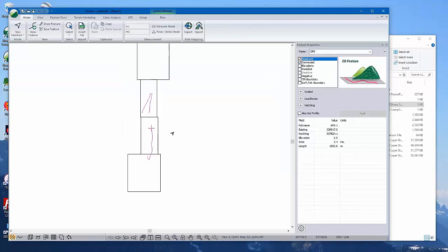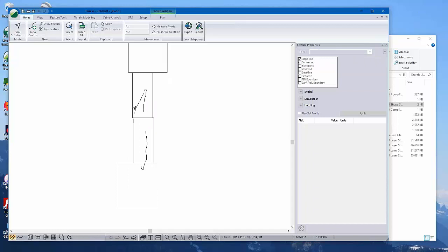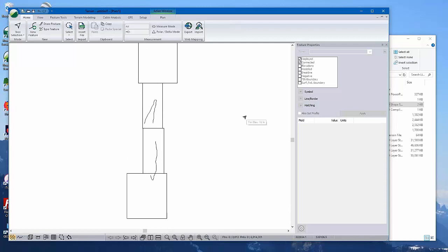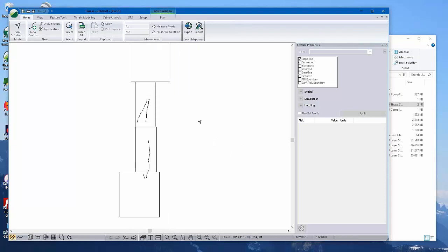So yeah, they need to be in the same coordinate system, or this is just not going to work. So there, I've brought in two road sections into my file. One of them straddles a couple of the panels. So the first thing I want to do, because I'm working on these roads, I've gone out and I field located these, and I want to use them as P-lines for my design. So when I do the design, I can reference those features, offsets to the field run traverses.